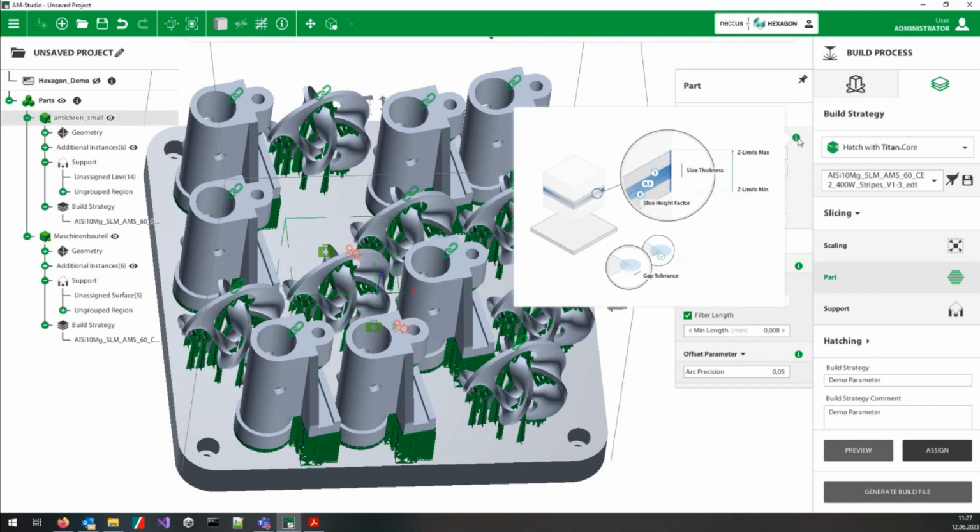So the 0.5 means that when we have 16 microns, the first layer will be energized at 8 microns, in the middle of the layer. It just specifies where the laser is focusing within the layer, if it's in the middle of the layer or at the bottom of the layer, that makes some difference.